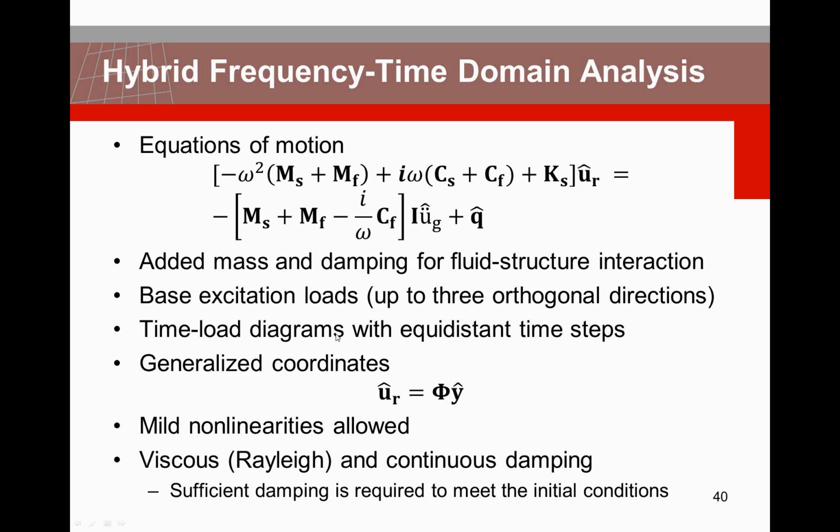What you need to take into account, because we are switching from the steady state solution in the frequency domain to the time domain, is that we need to have sufficient damping to meet the initial conditions. In case you don't have any damping and we calculate this steady state solution, it will look in the time domain as if your structure is already moving before your loading has started. That's because you calculated the solution in the frequency domain. When using sufficient damping, you can still match these nice initial conditions.